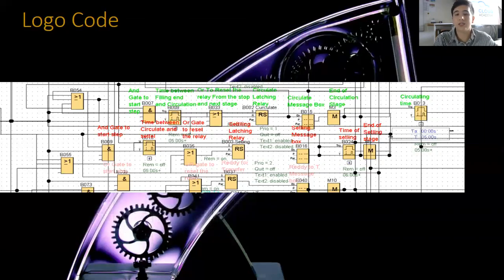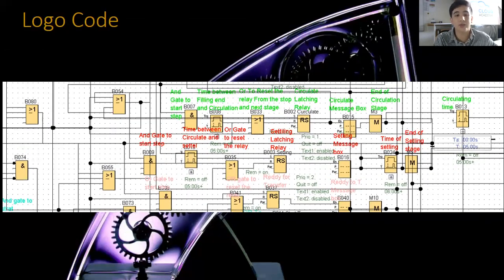The next sequences are the circulation sequence, the settling sequence and the ready for transfer sequence. They all work with the same foundation, with AND and OR gates to set and reset the latching relay, and have flags and message boxes to identify in which step it is. If it gets to the ready for transfer, which is the bottom part here, the program will look at input 4, which is the low level of the 2 clean tanks. If it's not below that level, it will not transfer the clean water and will wait until the level has been reached.